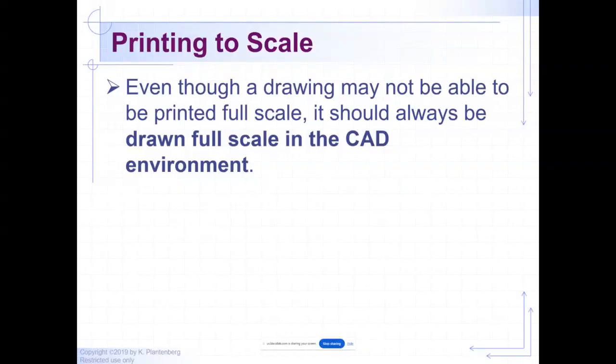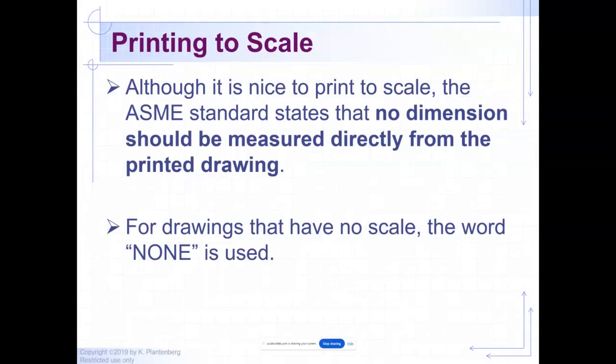However, even though a drawing may not be able to be printed full size, it should always be drawn full size or full scale in the CAD environment. So we always draw everything full size, period. Okay? That's something you should carry even if you don't use this. But if you do, you should definitely remember this. Very important. Always draw everything full size.